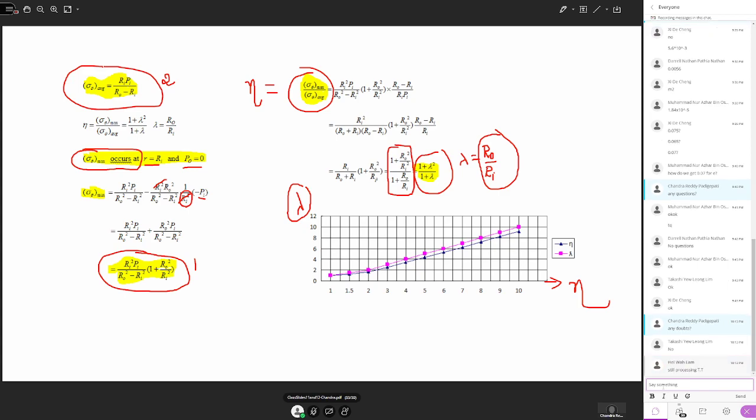The derivation part and other things you can read from books. What is important is, for a thick wall cylinder, how the tangential stress varies and how it is connected with the inner pressure, inner radius, and outer radius. Similarly, how the radial stress is connected with those parameters.